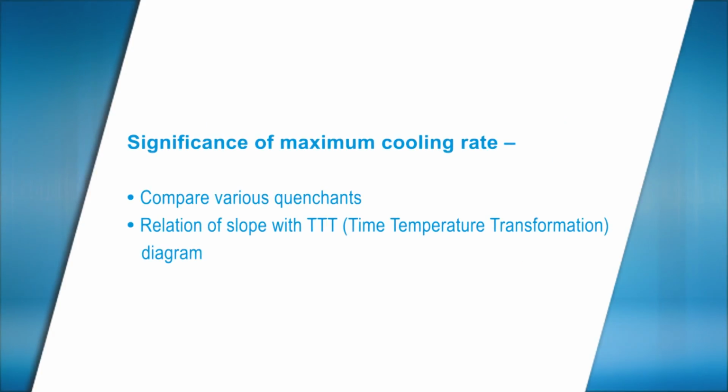Significance of maximum cooling rate. The maximum cooling rate can be used to compare various quenchants. The relation of the steep slope of temperature versus time curve and its position in relation to the time-temperature transformation diagram is of utmost importance.